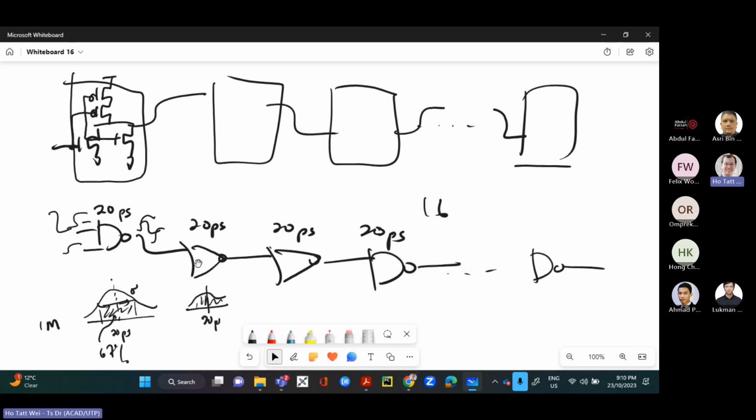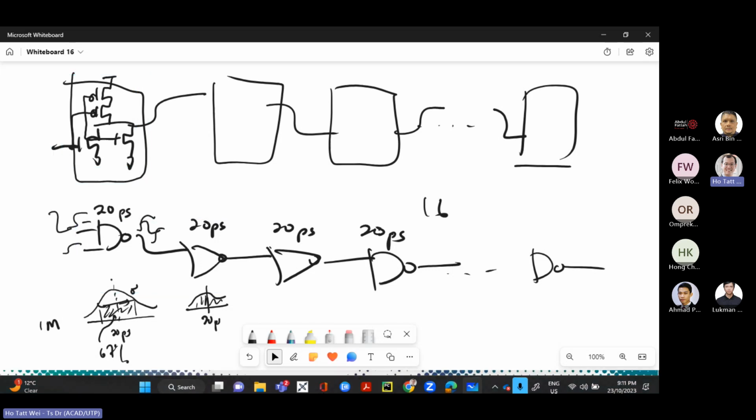And again, it does not mean that the delay is changing in one chip. In one chip, the delay is fixed. It's just that when you look at 1 million chips, 2 million chips, and you check that particular logic gate in those chips, you do a histogram, you will see that the delay in the different chips will follow a Gaussian distribution. 20 picoseconds is the mean with some standard deviation. And this variation arises from process variation: changes in channel length between each chip I fabricated, changes in the oxide thickness, and random dopant fluctuations, where the device has more or fewer dopants.